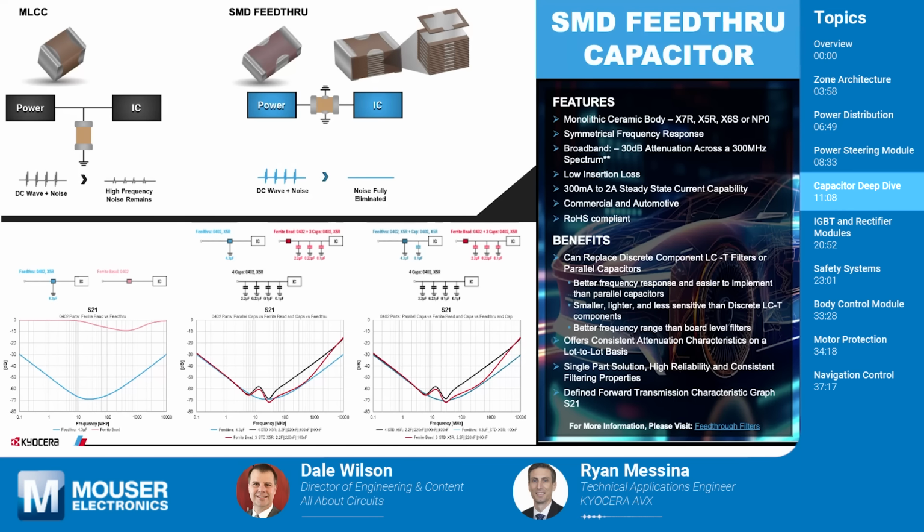And the idea of putting 4 of these down there is so that you can get a really broad range. So you can pull either low transmission noises, low AC noises, or high frequency noises. So you need multiple caps down there so you can reach all of them. You can get rid of all the noise that's coming in and have really stable power. Typically what you would do is either have a leading ferrite bead, like you see in the very middle section there, a red square and then 3 caps after that. That's to essentially give you low and high frequency broadband filtering. Or you have the 4 caps below that, where you're filtering out a broad frequency.